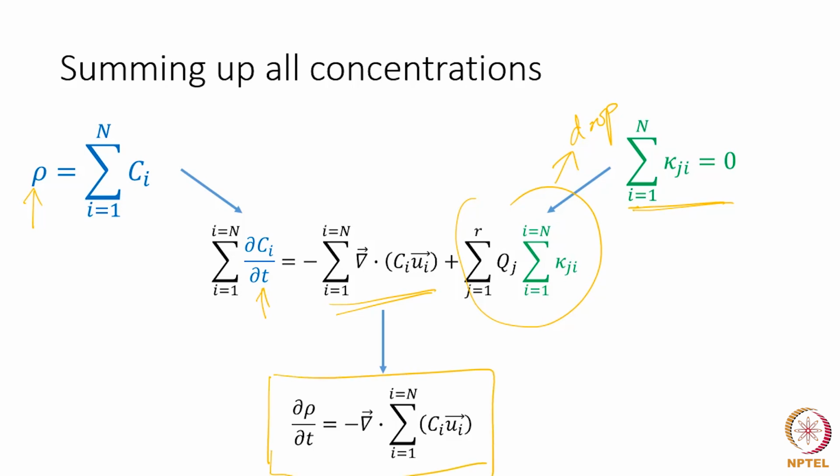So this looks quite close to how the continuity equation would look, but we still have to go a bit more, because we have here the velocity of the species i, and in the continuity equation we have u, which is basically the velocity of the material, and we have to find a way by which we can reconcile these two quantities. So what we mean by the velocity when we were doing the derivation in fluid flow is something that we need to define with respect to the velocities of the individual species. So that's what we would do here.